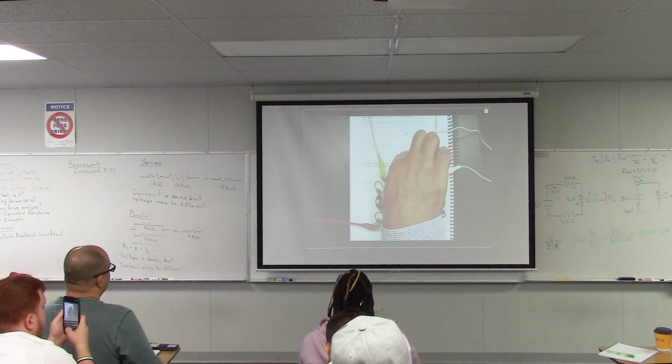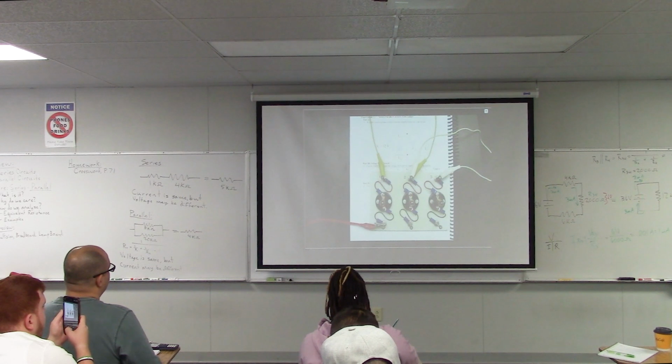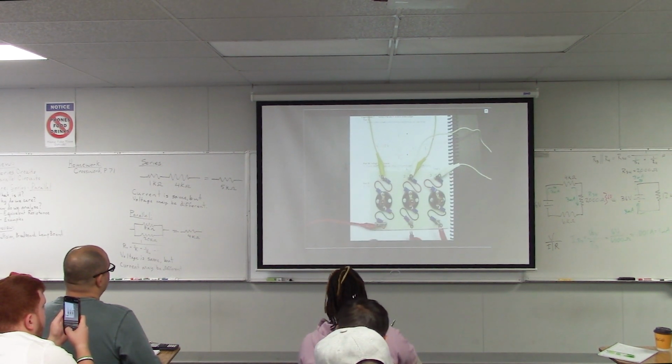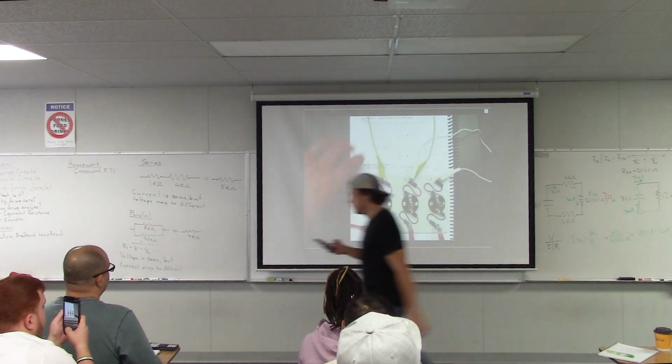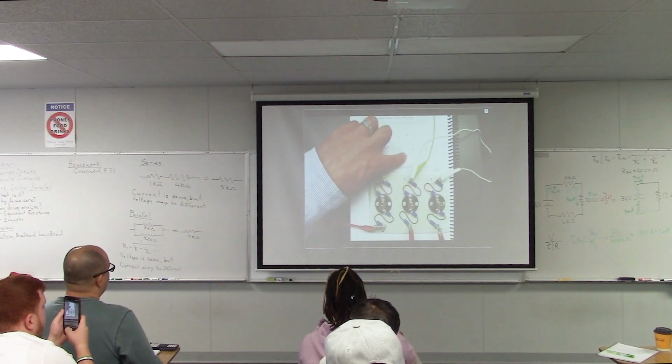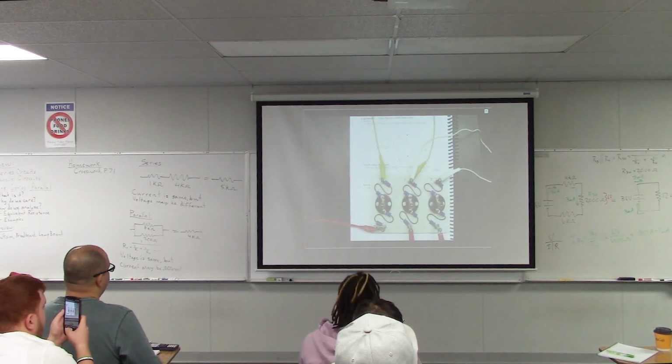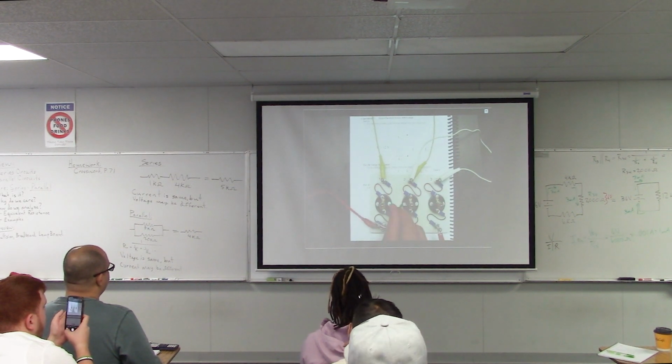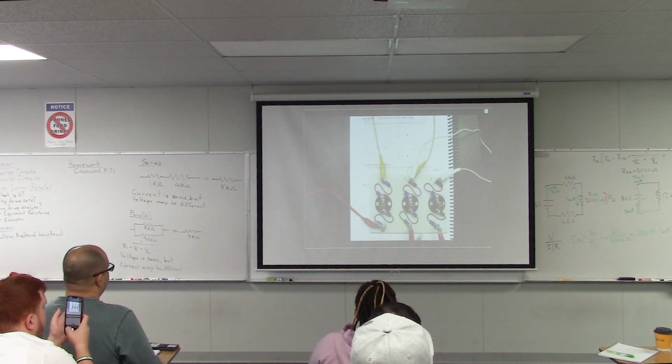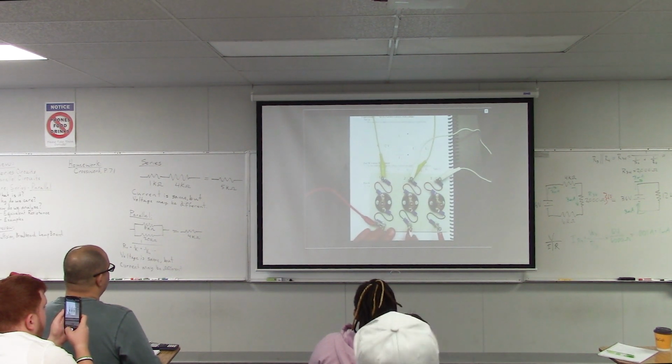The bottom of L2 is connected to the bottom of L3. So I'll do that. And then finally, the other side of the power supply is connected to the bottom of L2. So I'm going to take the other lead from my power supply, connect that to the bottom of L2. Okay? So that's how we set up this board.